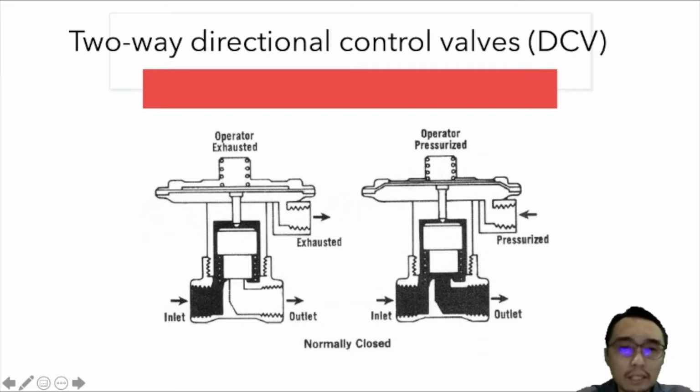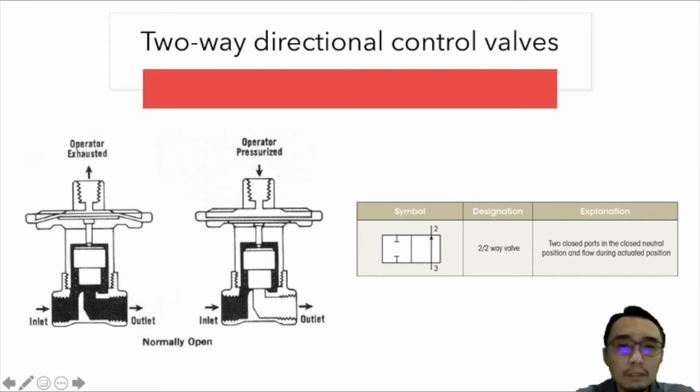Here we can see an air-operated, meaning air-piloted, two-way pneumatic valve. As shown, this valve is available to operate either normally open or normally closed. The poppet type construction provides a tight shutoff, and variations in the pilot air pressure or mainline pressure do not affect the operation of these valves. So you can see it's a two-way directional control valve as shown here.